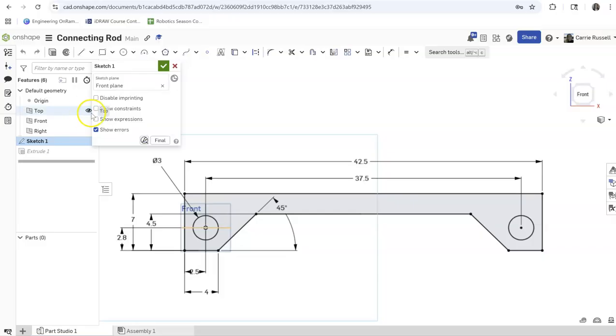And we're going to add in some chamfers. We're going to round these edges. So the chamfer tool is up here. I'm going to click these edges, and then I'm going to make sure that instead of a half or quarter of an inch, that they're 2 inches. So there's my first set of chamfers. I'm going to do the same thing to this side. I'm going to click, click, and notice because I had it on the other side too, it's good. I'm going to green check that. Whoops, click, click, hit enter,